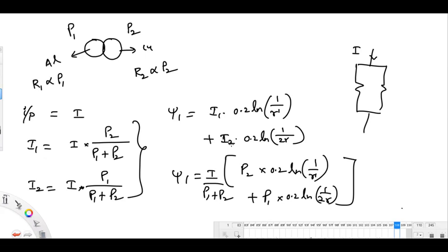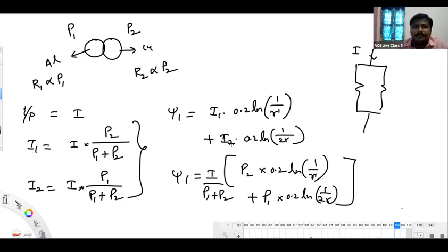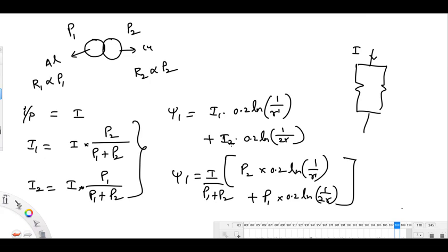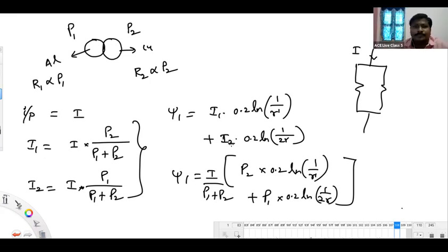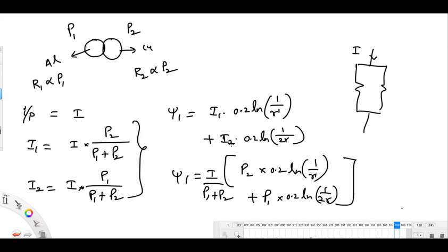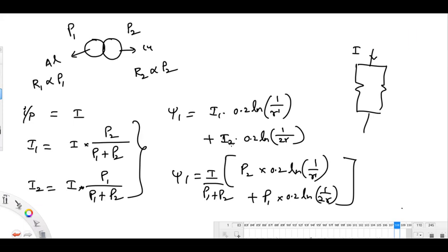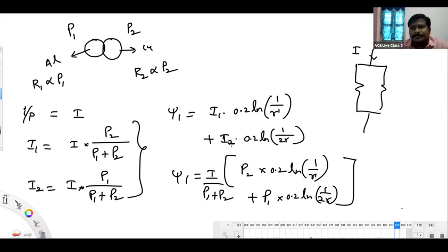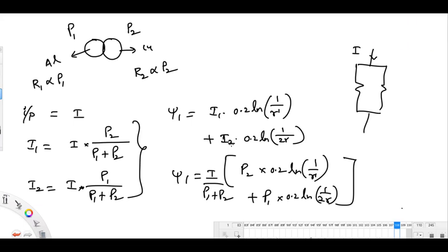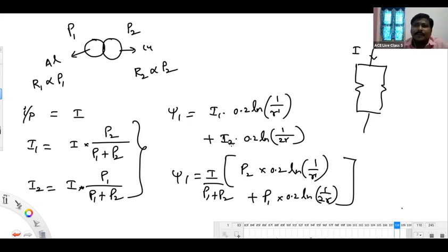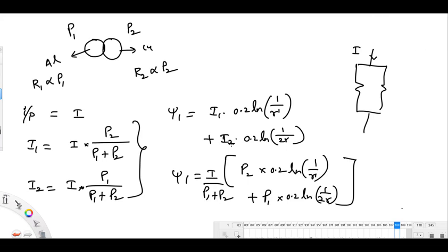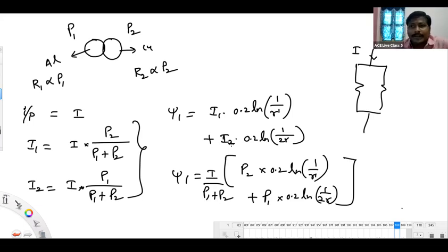Radius of circle or radius of conductor? Circle. Can we do the GMR for a circle of n subconductors? Yes, sir, you can follow the same formula. But here each conductor is touching. Okay, you can follow the same formula then also. And also an ACSR conductor can be treated as a hollow conductor by removing the steel. Because the center is removed, it becomes hollow. But if you have only one layer, if you have a number of layers, then this formula can't be used again. There, the thickness of the circle will be more, no? Yes, you have to identify. Okay, sir. Thank you, sir.